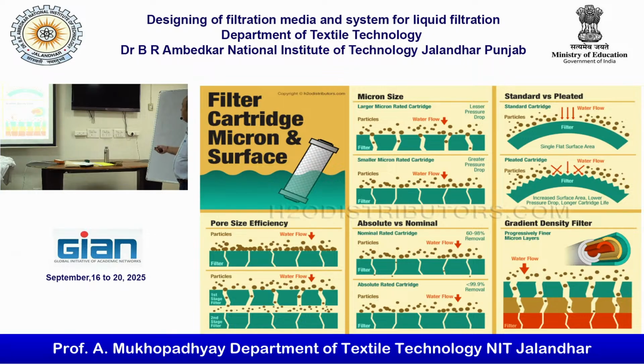Another aspect is standard versus pleated. Pleated can give you a larger surface area, but the flow direction will be different in the case of pleated ones. Another important aspect is the gradient density filter. In a number of cases, this is the new development where the pore size gradually becomes smaller and smaller. Instead of making a uniform structure of pore size, it is better to have larger pores initially, because that will give you the energetically more favorable condition and greater particulate capture.